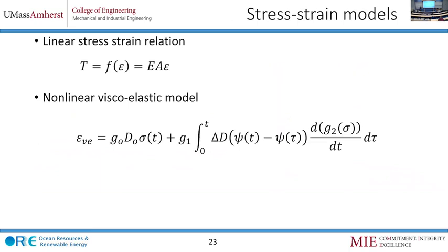So, just a couple of slides of math here. We know that for a linear stress-strain relation, the force is related to the strain through the Young's modulus. And when you take tension over area, you get the stress directly related to the strain through the Young's modulus. In viscoelastic models, this is the Schapery model, published in 1969, still widely used. In a nonlinear viscoelastic model, you actually have the strain, epsilon sub VE for viscoelastic,